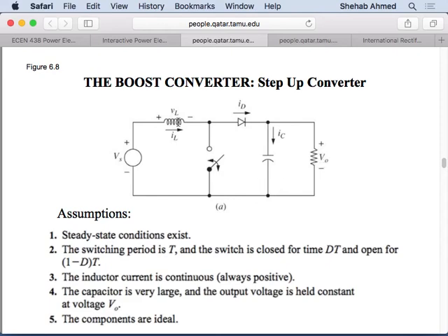So if I store more energy in the inductor, I'm able to increase the output voltage. If I increase the output voltage for the same value of resistance, that means I am increasing the average value of current. This average value of current flowing in my load is also the same average value of current flowing through my inductor. Do we agree or not?